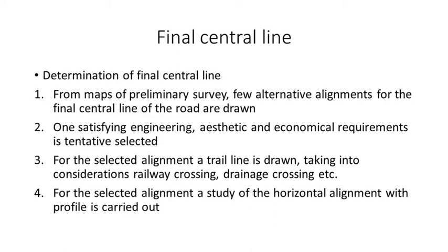Next, what is the maximum and minimum rainfall, and what is the highest subsoil water level? That data should also be collected for that particular selected area. Okay, again, what is the nature of the cut section? Some trial pits and some boreholes.